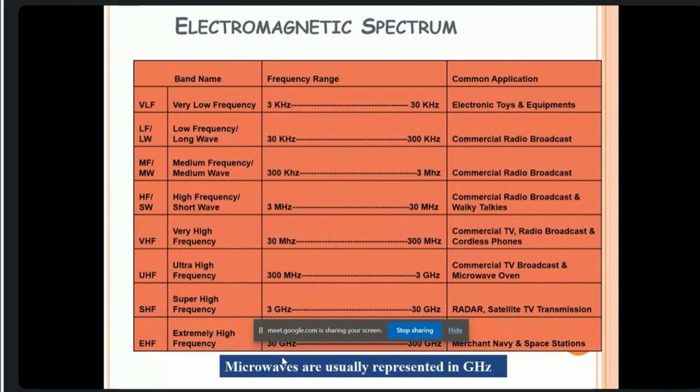When we take the example of a filter, if it is very low frequency, we will go with the LC or RC filter, that is resistor, capacitor, resistor, inductor filter. But the same thing at high frequency, particularly beyond 300 megahertz, cannot work. So we look for some other component. We should know the reason why these so-called lumped components, the discrete components, that is resistor, inductor, capacitor,